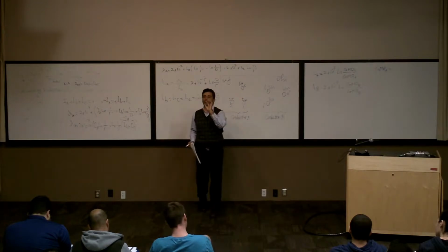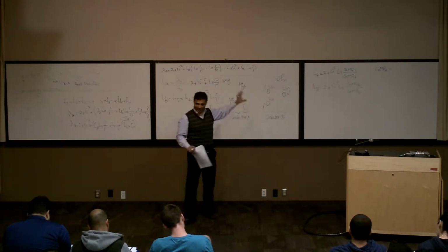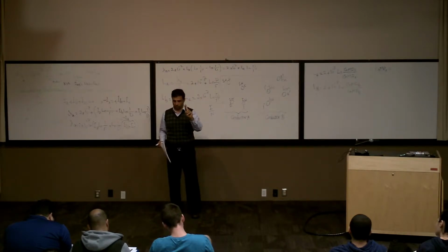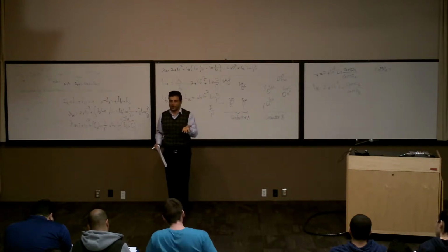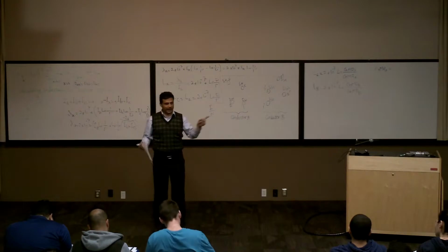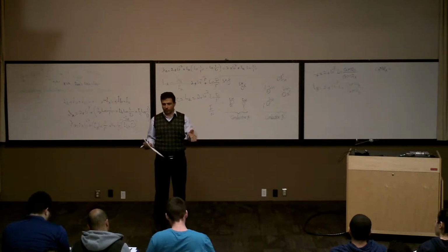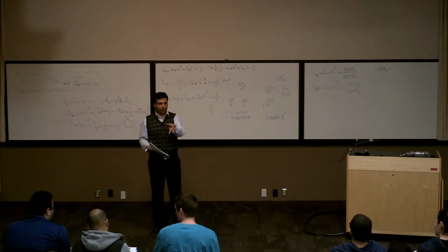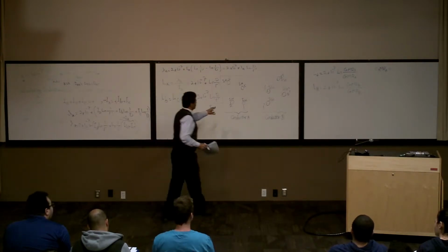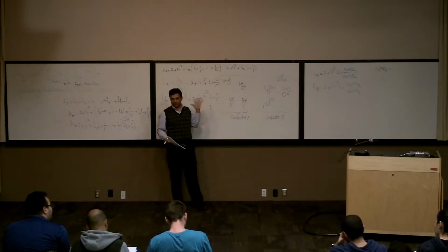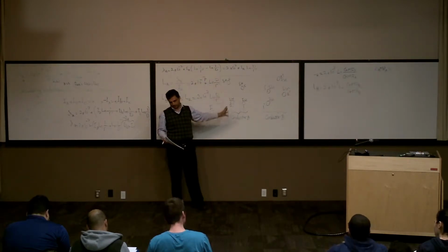I model it with one conductor. I have N here. I'm going to come up with the equivalent of one conductor, but I should say how much is R prime for that, right? We know if we had one conductor, it was very simple. We said okay, D over R prime, where R prime was the radius of the conductor. Here we don't have one to say, okay, is this one or that one or that one. We have N of them. Somehow we should come up with the average of these.